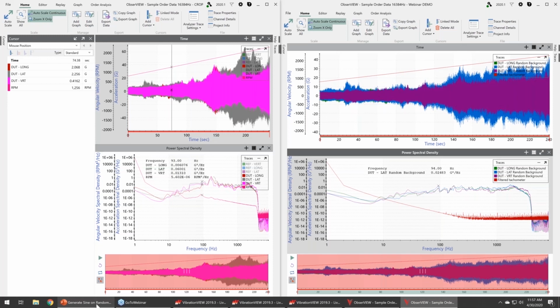So again, it's an engineering decision, but you have to be careful not to over accelerate the profile. You know, I can't run 10,000 hours worth of life in 10 minutes. That's not really how it works. So you don't want to over stress the item, but you do want to accelerate the test. Comparing your test results, the actual failures generated, or the test results in themselves to the original data with the same acceleration parameters would be the best method.